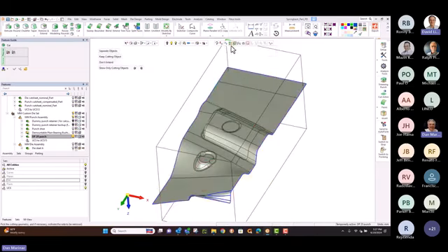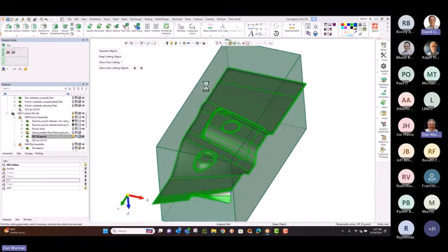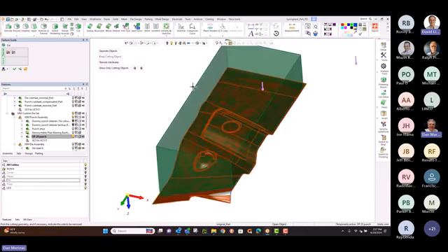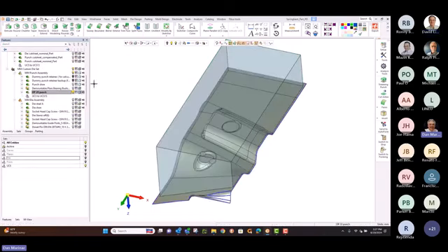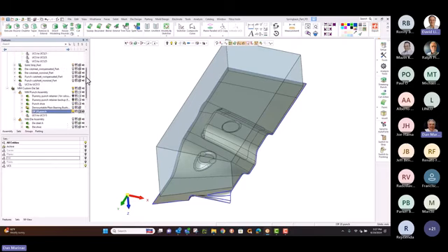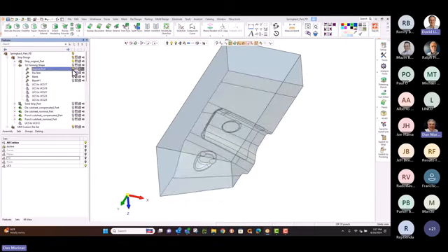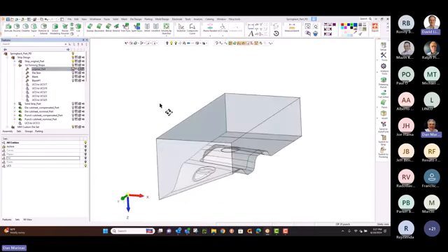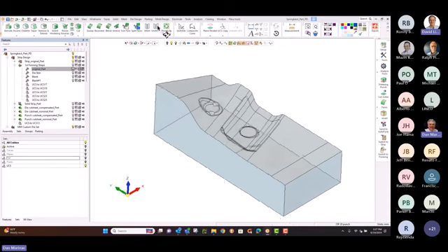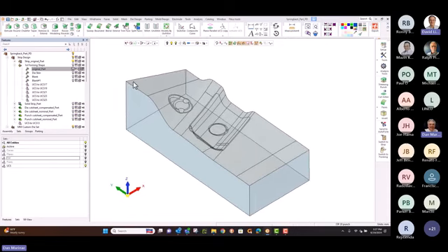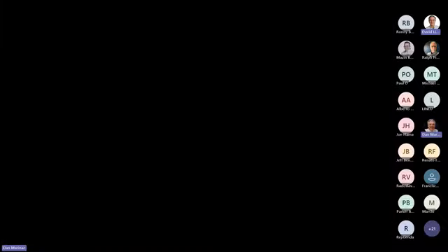Here I've got the offset punch sheet. I'm picking my punch block, and from there, let's say pick that punch sheet. Now I've cut it back to get the opposite side of the tool. So fairly quickly we've incorporated it. You've seen how we can apply the compensation for spring back and then apply it to the tool. And the nice thing is if I go back and change that percentage I'm applying it by, I can continue on, update it, and I can be confident that the tool will be updated to that amount of percentage.